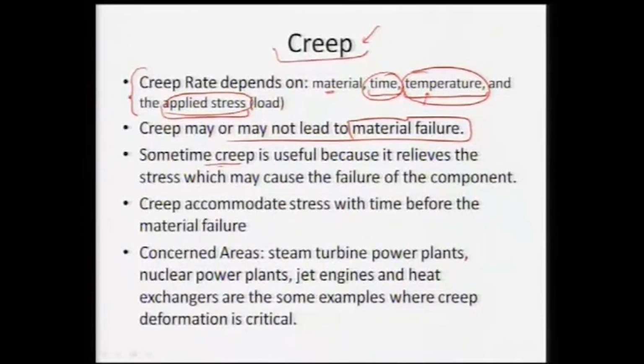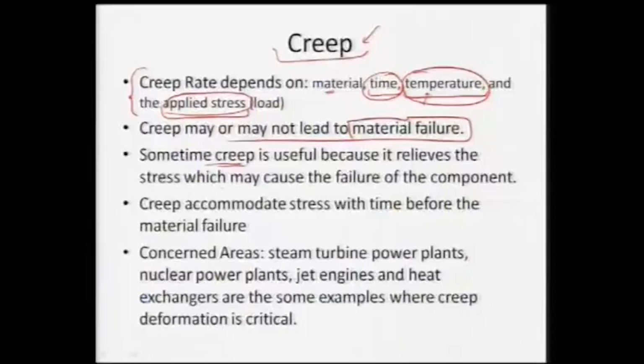But sometimes creep is very useful also, because if a material has incurred much stress because of certain processing, and once we heat it to high temperature for long enough duration, it can relieve those stresses, because now the yield strength of the material has been reduced. Now, it can release its stresses which might have been incurred during the processing or even during the functionality, when the material is being utilized in service. So, that can relieve the stresses, and that can avoid the failure of the component in that sense. So, sometimes creep can be a little bit useful, but it has to be in a controlled fashion.